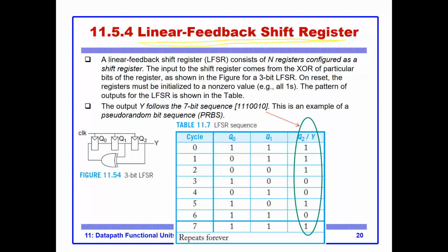So the linear feedback shift register creates random numbers, but let me add the word pseudo random numbers. Pseudo, what do you mean by pseudo? Well, it's kind of random, because these random numbers behave according to a mathematical polynomial. And if you know that polynomial, you can predict those numbers, but they act as if they are random, and therefore we call them pseudo random. That's one thing. So they are the output of a mathematical formula.